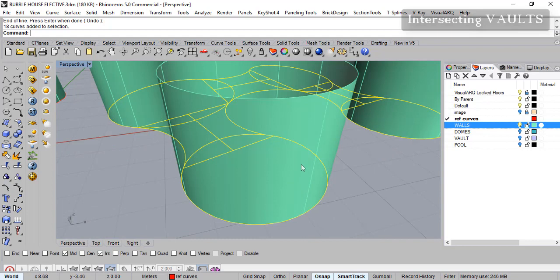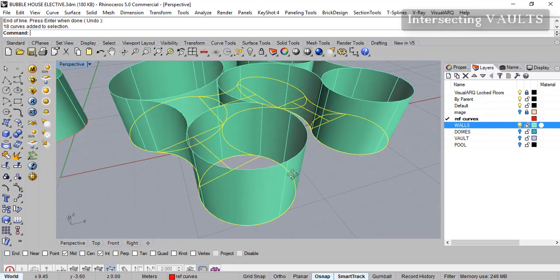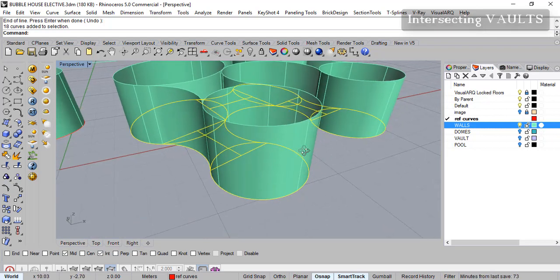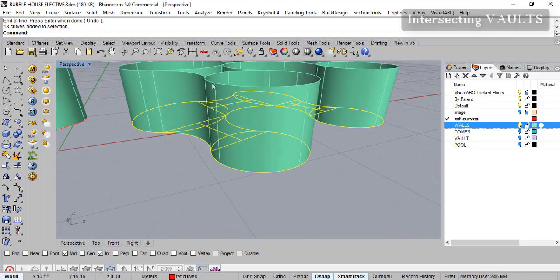And we need to move from a base point. So where do we want to move it from and to? We can move it from the ground center line. We can take one of the center points of the circle and then go to the center point of the top circle and move it.